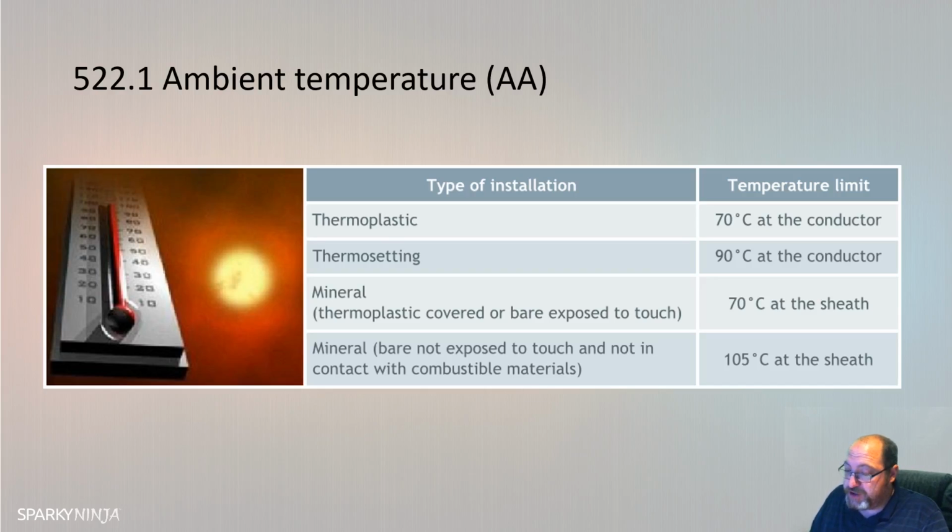So the next page shows you the environmental guidance. If you turn the page and you go to AD, you'll then see when it gets to AD, negligible, free falling drops, sprays, splashes, jets, it shows you the equivalent IP codes. So the IP codes are here in the book, referring to the external influence category.